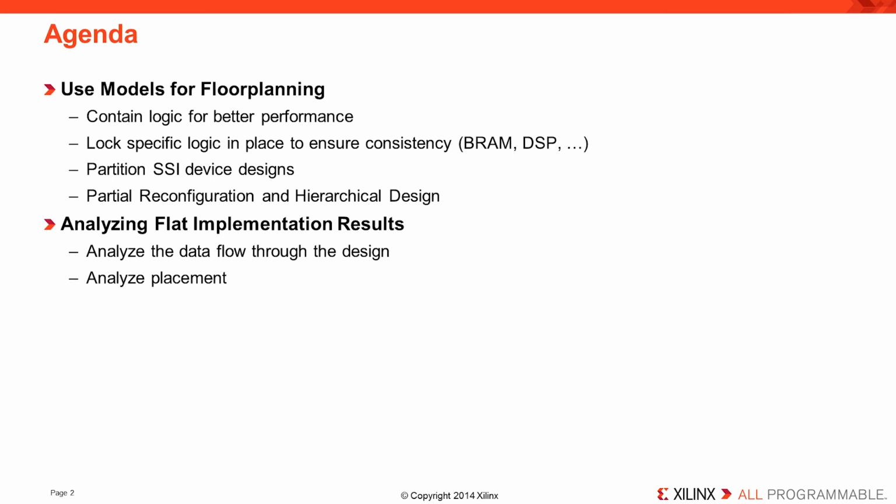We'll then show you how you can analyze the flat placement to understand where and how you might want to floor plan your design. And then we'll look at timing issues. Where in the design are you struggling to meet timing, and where might floor planning help? We'll walk through the process of creating physical blocks or P blocks. These are the rectangles that are used to contain the logic for floor planning.